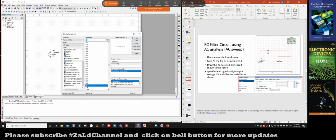Then another one is the 100 nanofarad capacitor. Which group does the capacitor belong to? The capacitor also belongs to the basic group. Find the capacitor, and find the value of 100 nanofarad. This is micro, and I don't want micro. I want the nanofarad one, which is N. Let me search for 100. This is 100 pico. I want the 100 nanofarad, which is this one.